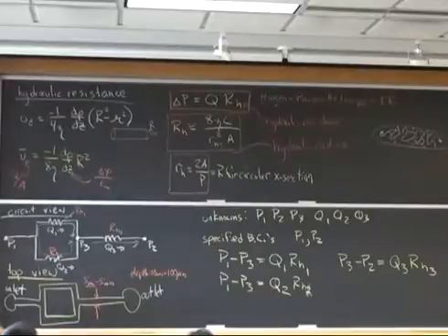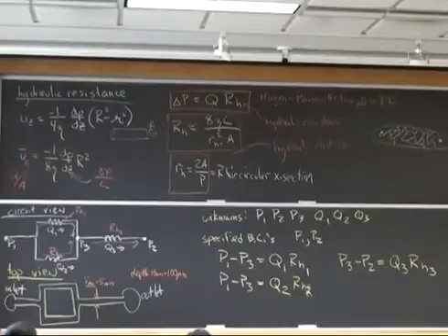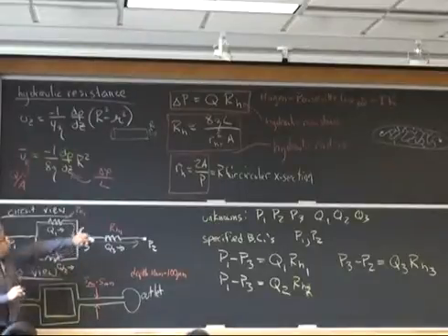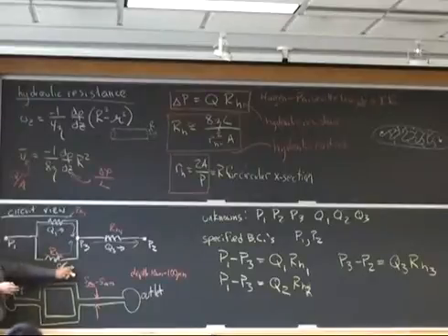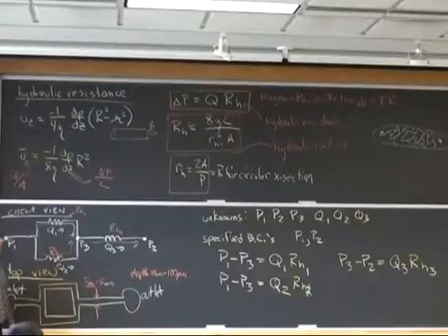Yeah? And how shall I add the currents? Right. I've used the momentum equation to define the Hagen-Poiseuille law, but I haven't satisfied mass conservation. And so mass conservation in an incompressible fluid says that the volume that's going into a tube always comes out of that tube. And the volume that goes into a node always comes out of that node.